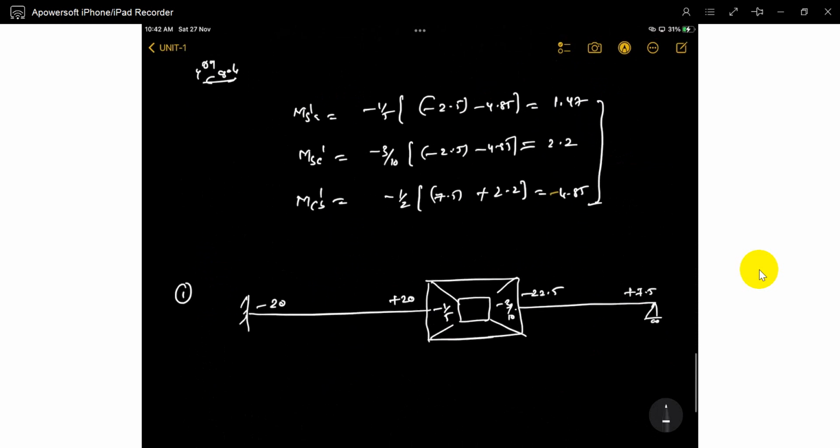So you don't want to take it, it is an extra kinematic indeterminacy, no? You already know in displacement methods, if the kinematic indeterminacy is increasing, the iterations are increasing to find out the unknowns. So we can easily do it. It is a hinge joint, the final end moment goes to 0. You already know it. So for that you have to apply minus 7.5 here, and it goes to 0.